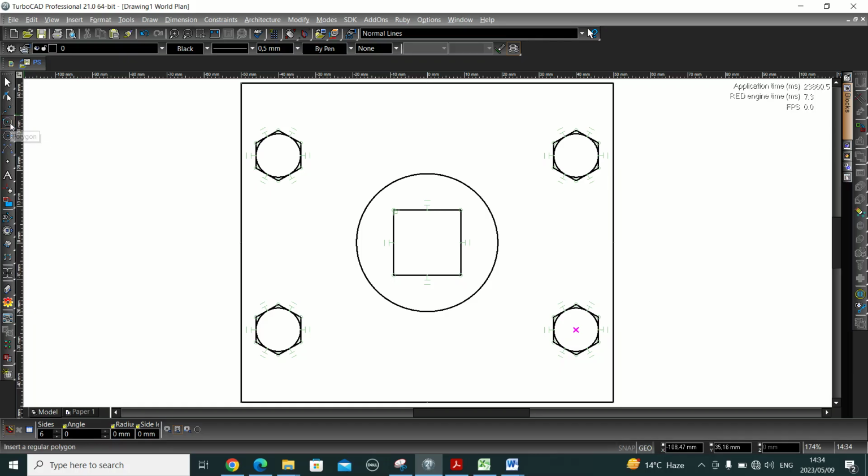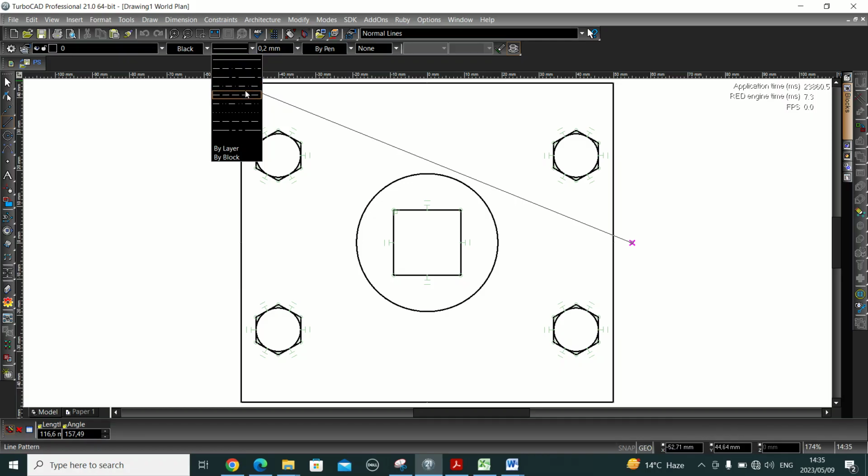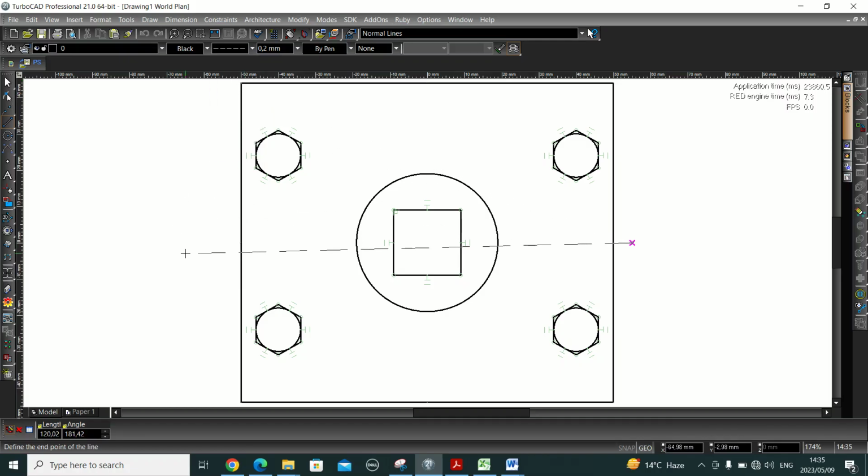Let's draw that one. Go to where you've selected the polygon, click and hold, select the line, change the size to be 0.2. Press tab now. X will be highlighted. For X, we said it's 55, Y is 0. Press enter. You see I have a line. I needed to skip a step of changing that to dash lines, which is hidden detail.